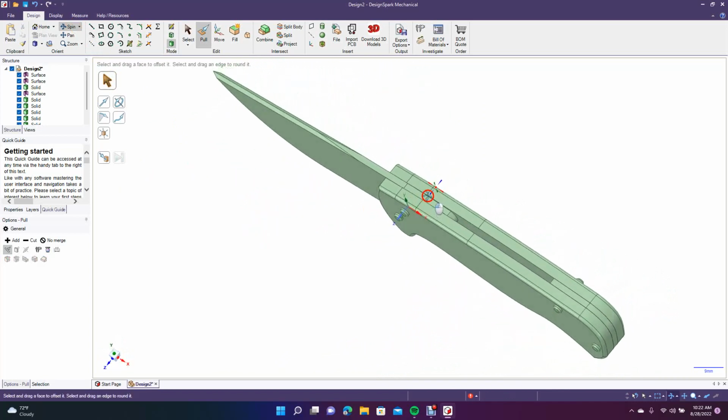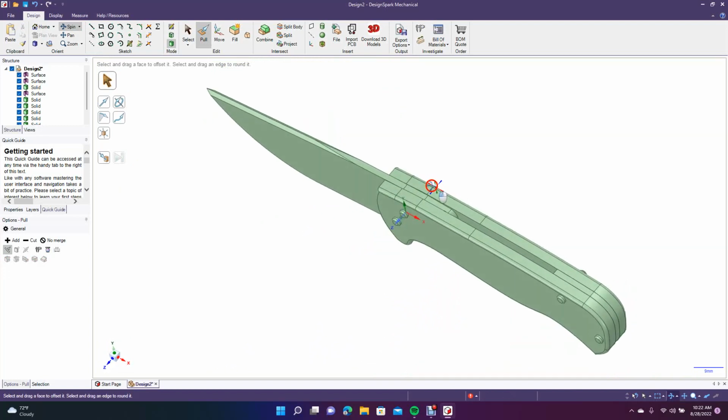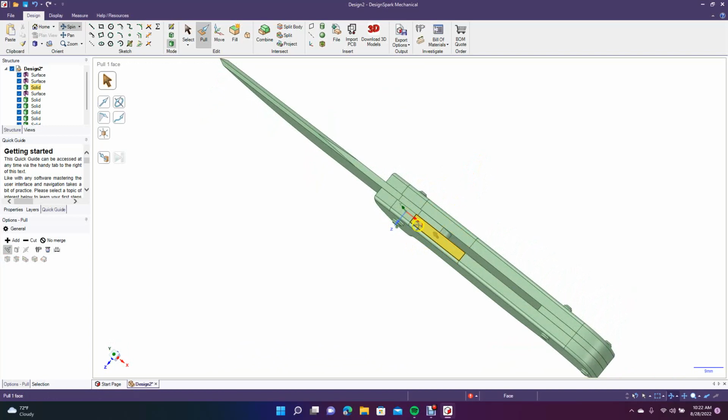What you would do if you were creating this is you would actually get these kind of screws. You just get them the length here. So this is 4 plus 2 plus 4, so that's 10. So you maybe get these, I don't know, 12 millimeters. So you would have 2 millimeters over here and 2 millimeters over here, the kind that thread in, and you screw them together.